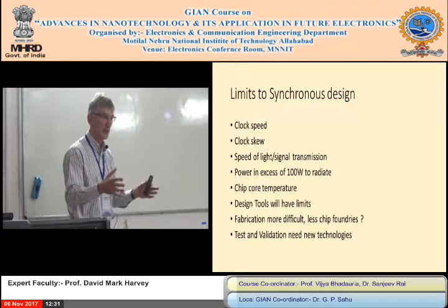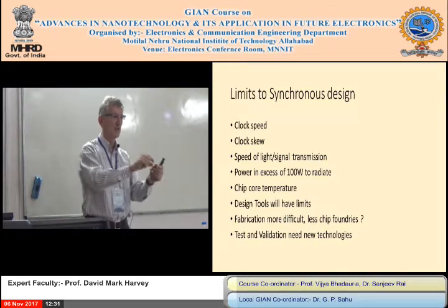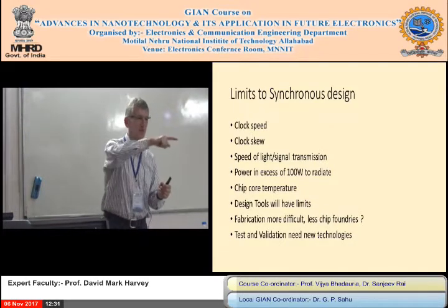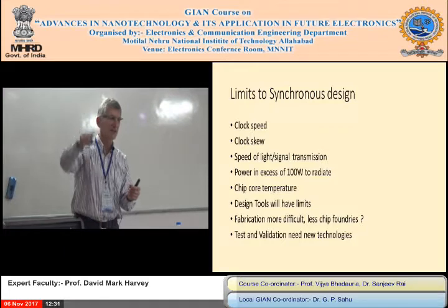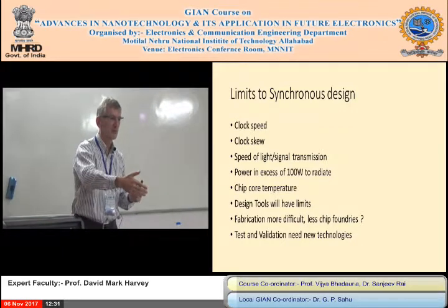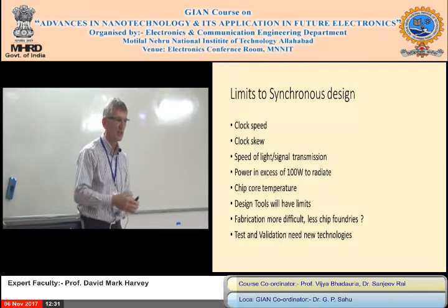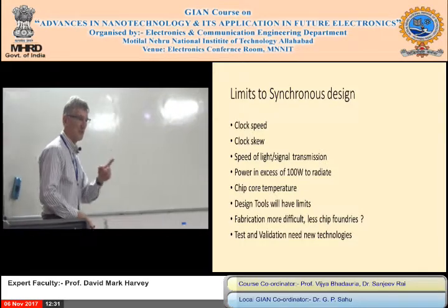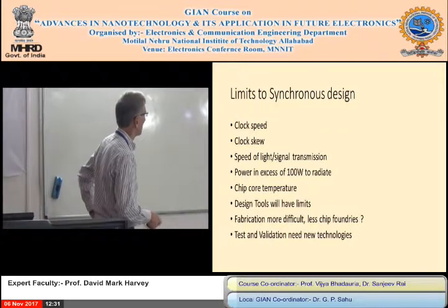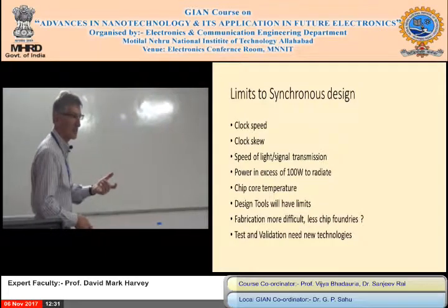So if you do an auto routing, some auto router will say, here's your chip, I've routed all your chip, there's one gate I can't route. I'll put it in the top corner. You might just do that. You use that last bit of silicon, then it routes the connection up there to the chip and back. By the time it's come back into the gate, another signal's come along before it, it goes out of sequence. And this is the sort of transmission time we need to think about. So be aware of auto routing. Don't think auto routing will cure everything. So that's speed of light. So signal transmission and switching times need to be taken hand in hand.